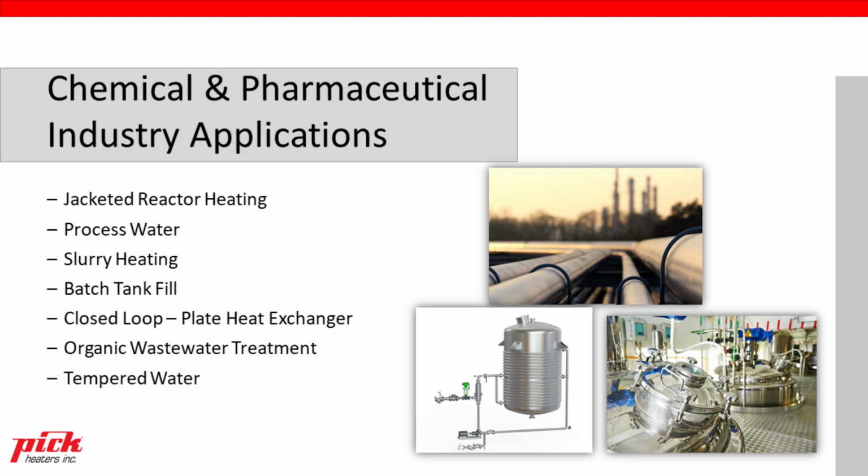It has many, many advantages over using steam or heat transfer fluids because hot water can evenly heat that reactor vessel instead of having hot spots from steam and dealing with getting rid of that excess condensate after it's condensed. So circulating water is a natural fit for that.